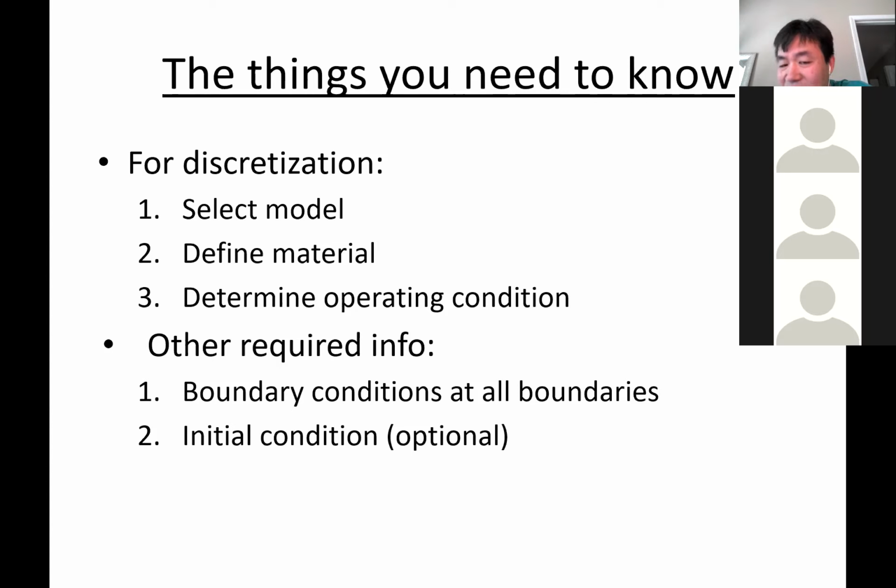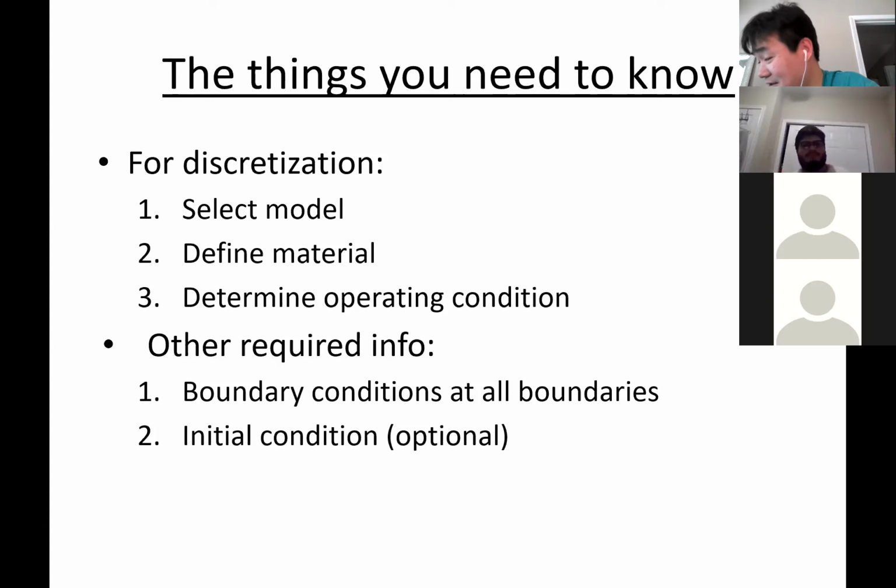And determine the operating conditions, okay? Are you simulating under Earth's gravity, or under Mars gravity? Or are you simulating the environment of the Moon, okay? So set the right operating conditions. It's very capable of doing many other situations, so it's up to you to specify. Okay, so operating conditions. What is the reference pressure? Where is your reference pressure? Questions like those, you have to answer yourself before you can actually select those conditions. Okay, these are related to the discretization and the models.